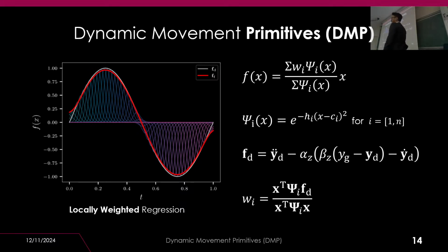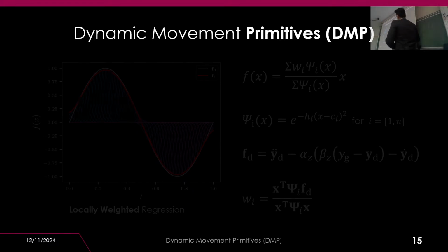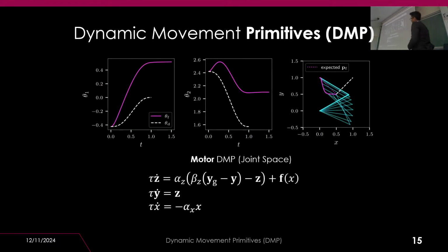Basically, the set of weights W is our DMP, our representation over an embedded space of Gaussian kernels that represents the dynamics of a given movement, of a given behavior, of a given task. This method, as I mentioned before, has been applied over the joint space, and as you may notice, although rather functional, our expectations of reconstruction are not met by the system.